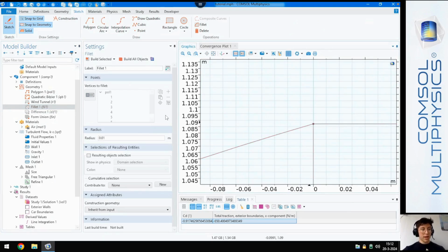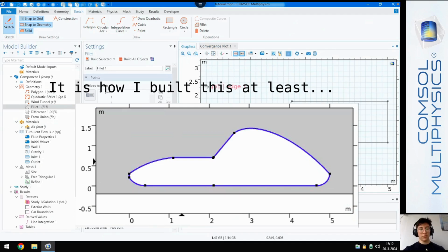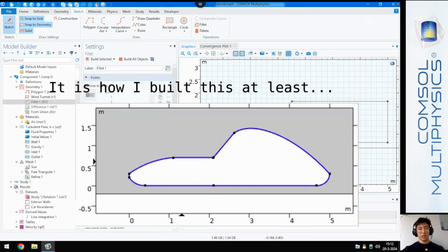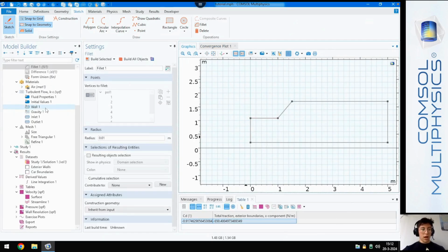So you're going to want to do that, and then again apply, get out of sketch mode, and once you have solids, apply the difference modifier, and then just repeat the process. But it's a pretty good workflow, I found, for changing the topology. It doesn't take that long once you get used to it, but it will take some getting used to.